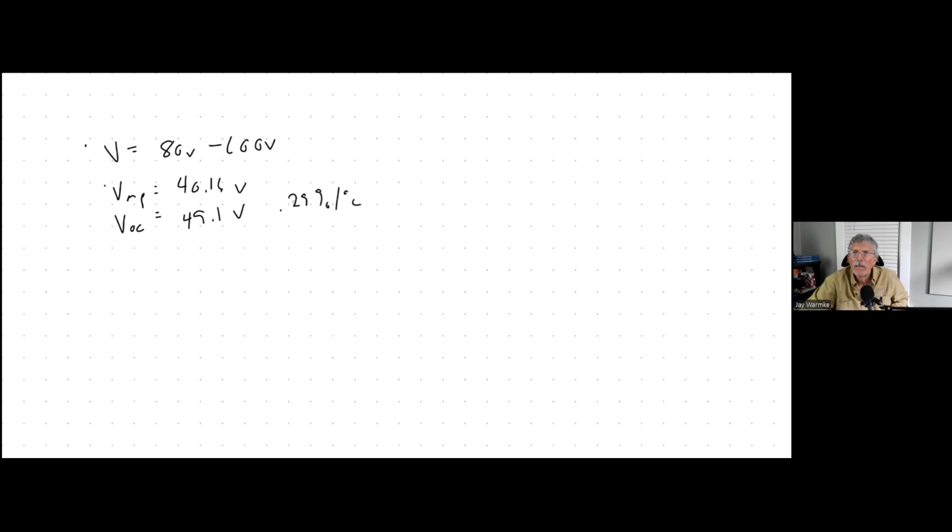And at Pmax, 0.35% per degree Celsius. All right, so these are the specs that I needed to know. And now I will also need to know what is the coldest temperature ever experienced at that location. So we said this was Boston. We'd look it up on the internet. Let's say that we decide it's minus 39 degrees Celsius.